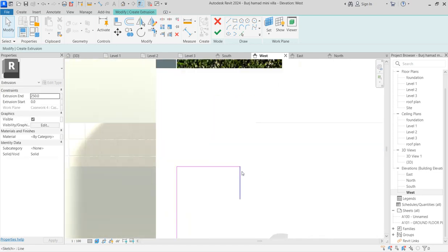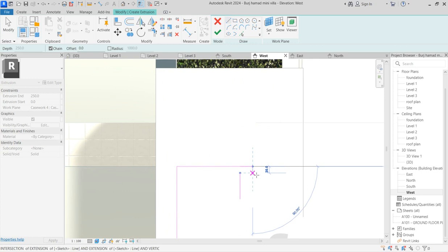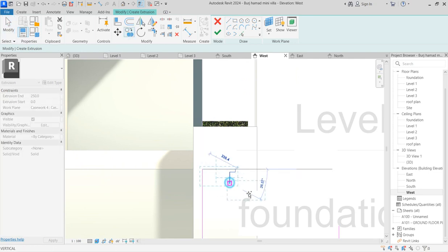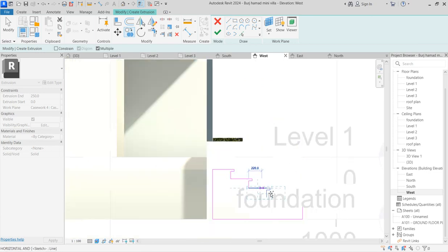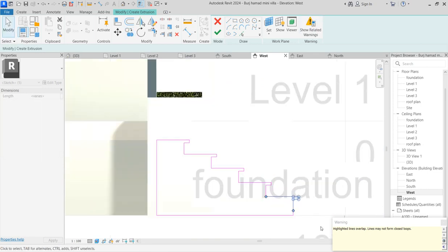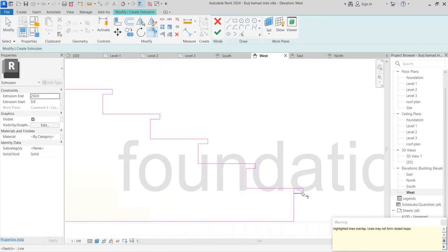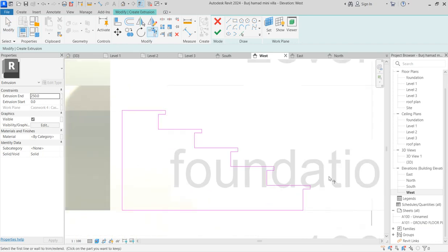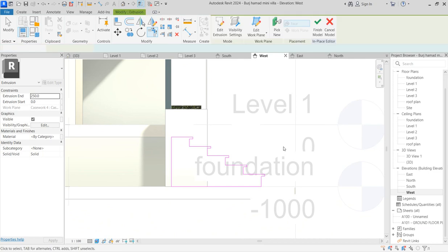So now what you do, I want to create a beautiful nosing for this particular step. So my nosing is going to be like this. So I'm extending it. Good. So we have the nosing. Then you begin to copy from point to point, from point to point. So it gave me some warning. It does not matter. What you just need to do is that you delete this. Then you specify this one. So that is it. You click finish.